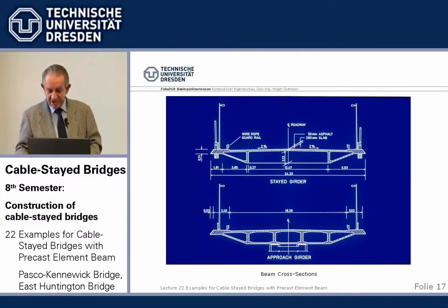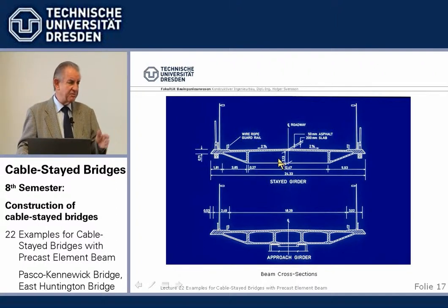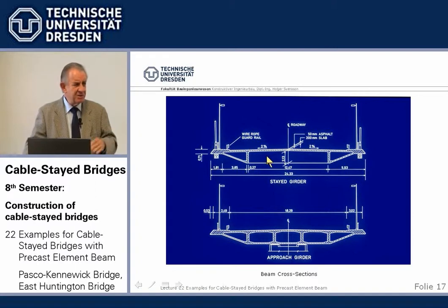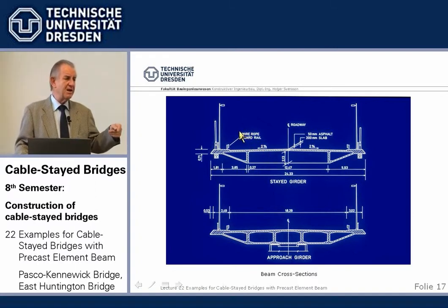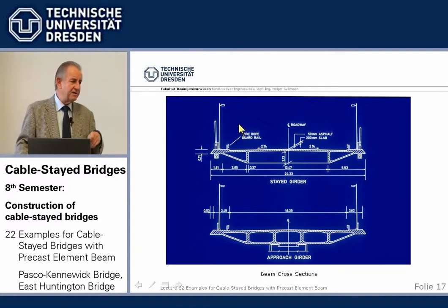The beam was on one hand aerodynamically shaped. First of all, this was basically designed by Professor Leonhard himself, which we then realized. Low deck depths, 2.2 meters if I see it right, for 300, so it's 1 to 140, which at that time, that was early 70s, was rather low. You remember Helgeland, we later went to 1 in 350, but this was one step there.